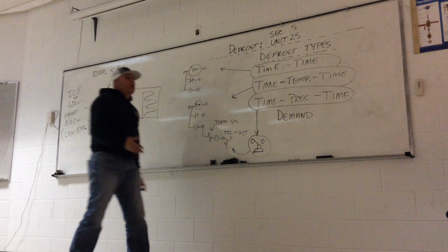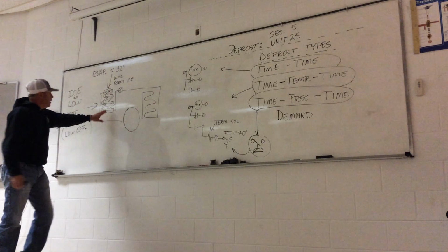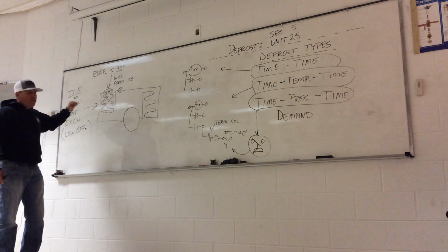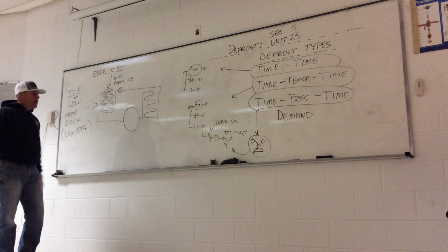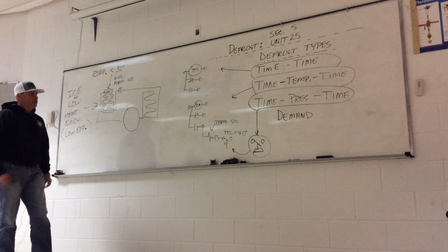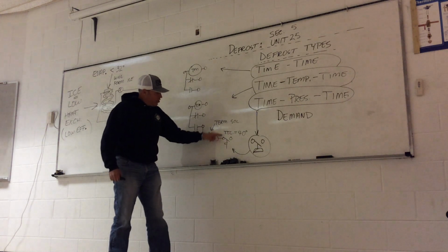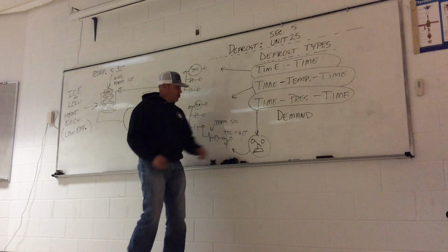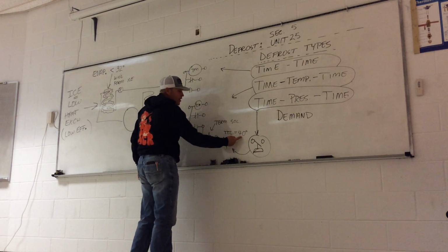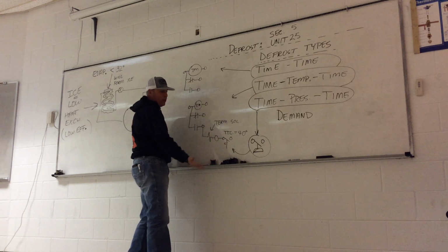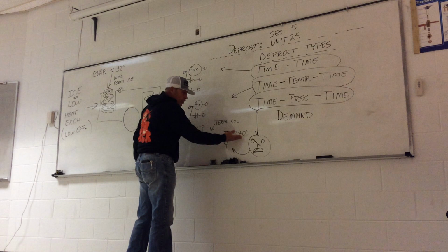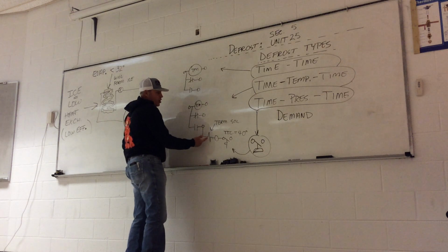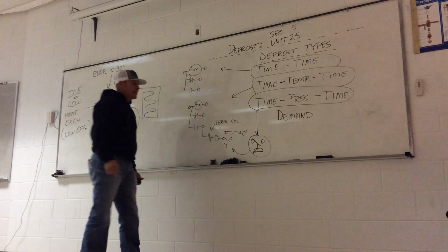So if we start heating up the evaporator, the pressure on the low side would start going up in conjunction with the temperature. Temperature and pressure have a relationship. We've been learning that since first semester. And so instead of having a termination temperature control here, we would have a termination low pressure control, still corresponding to 40 degrees Fahrenheit. If our low side pressure got up to the 40 degree pressure-to-temperature relationship, the TC would close, which would energize the termination solenoid, which would take us out of defrost.